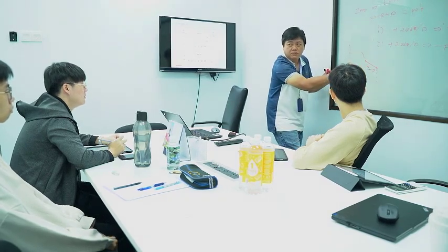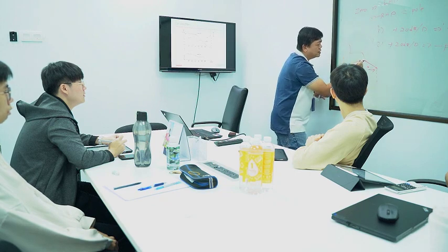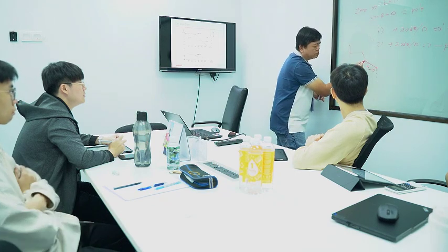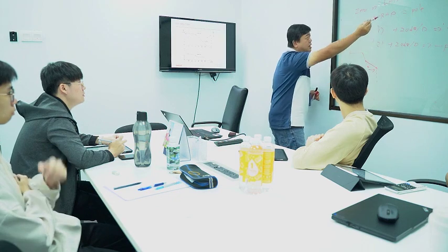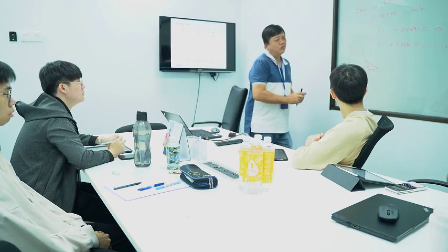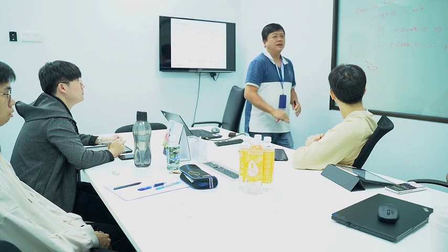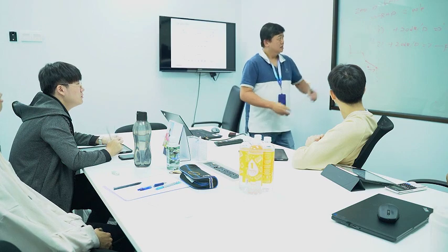You look at the curve, more phase shift will be there, right? Actually, this one, at least it will be a pole, it just makes it even smaller, huh? The UGF will increase, right? But for the RHP 0, it increases the UGF further. Normally, if you have wider UGF, you have more phase shift, right? That's why I say this is worse than a pole.